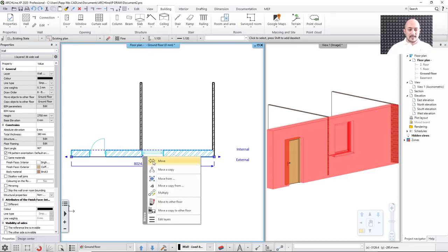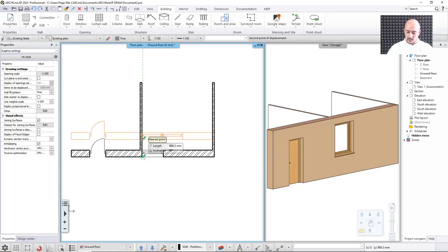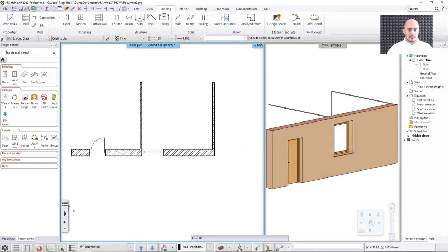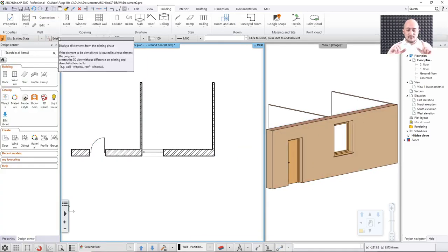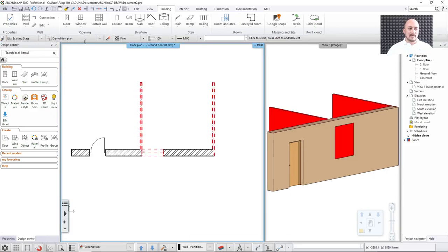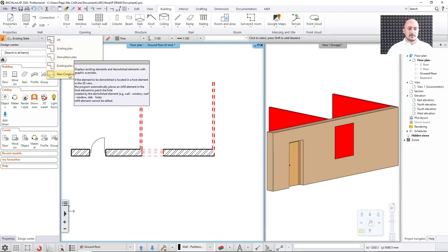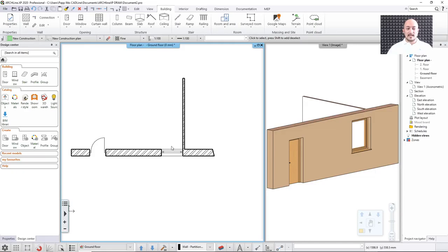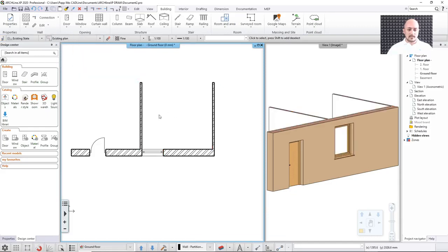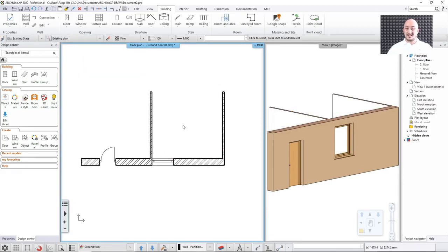So when I click here and I say, okay, move it up, I don't know, this should be 50 millimeters. So just move it like that. Then now everything is, let me just undo and redo that. So I made that little tiny tweak, but now all those are reflected in all the design phases, in the demolition plan, in the existing plan after demolition, and of course in the final phase in here. So this is what we achieved with this one. Okay, let's go back to the existing plan. So this is how you can make corrections, and it's very easy.